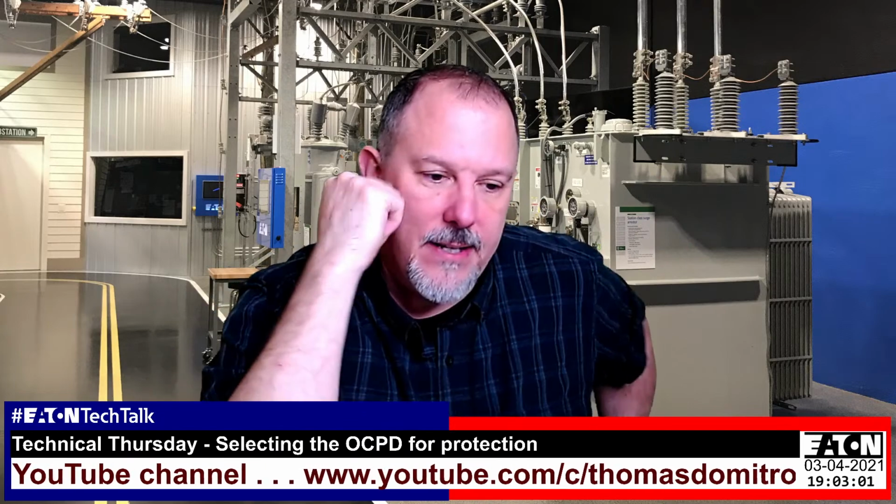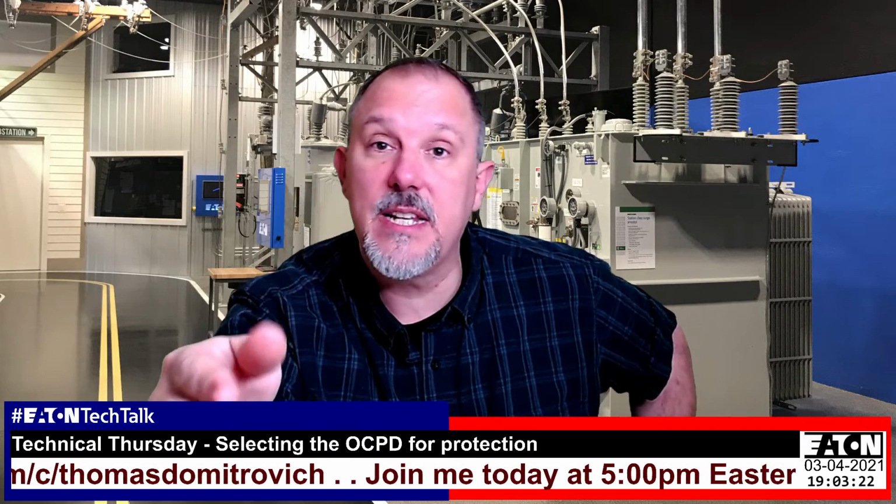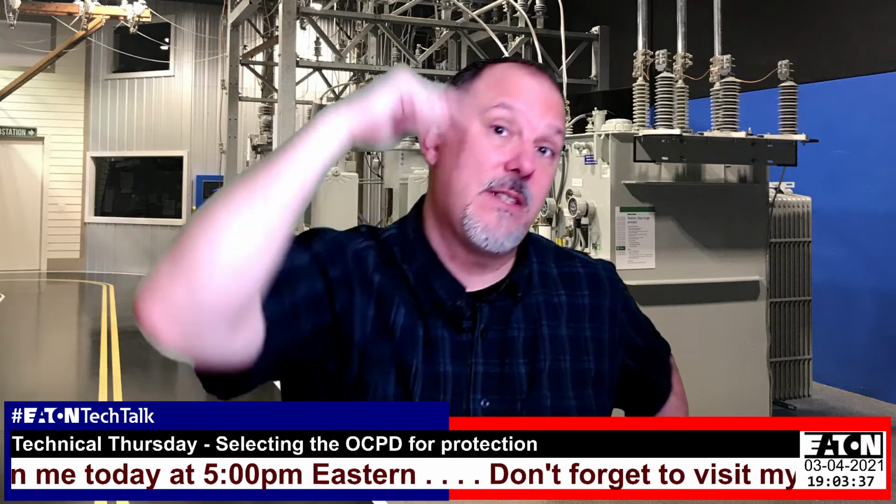So here's my thought process. I think that in 240.87, zone selective interlocking and differential relaying are really about equipment protection, not so much personnel protection. We've been using ZSI for years in petrochem facilities and pulp and paper and universities and things like that to, if there's a problem in the gear, we clear it really fast. I'm not calculating an incident energy based upon that clearing time, the upstream.